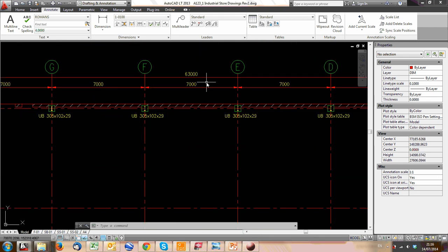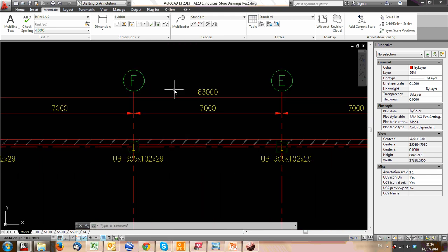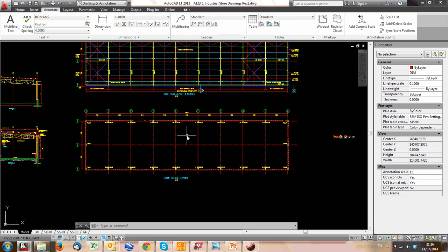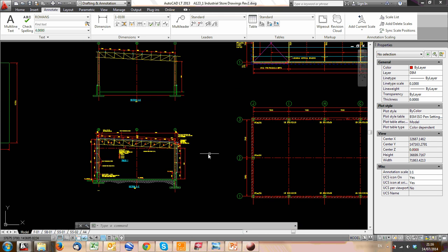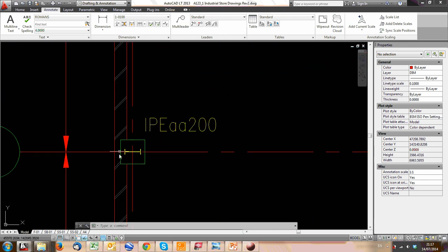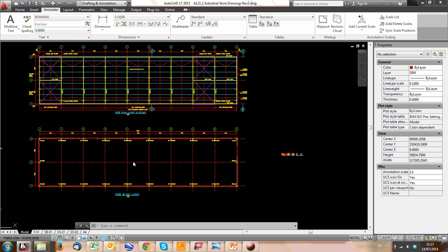This is a very important drawing between especially your civil contractor or your building contractor, the guy who is going to do the concrete, and then your steelwork contractor who will do the roof. Sometimes they're the same, sometimes they're different. It really depends on the job. So there you need to give them a detail of how the bolts fit into each piece of concrete and where the bolts go.